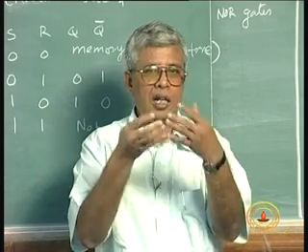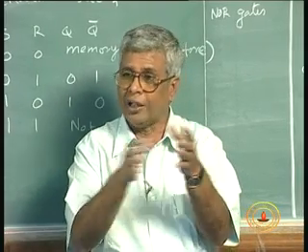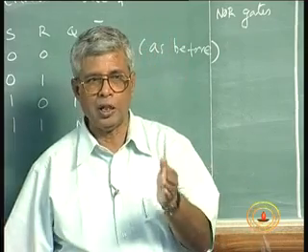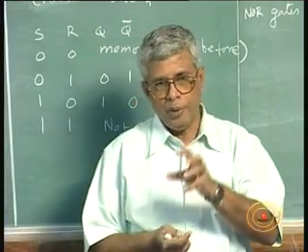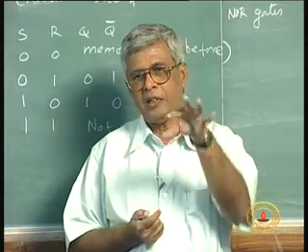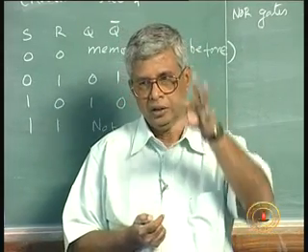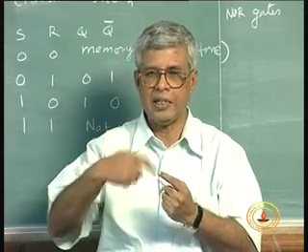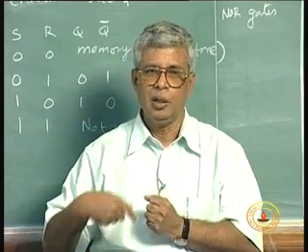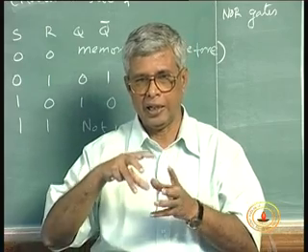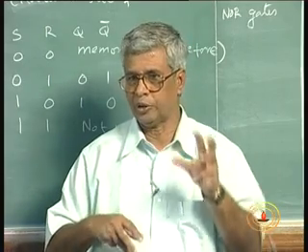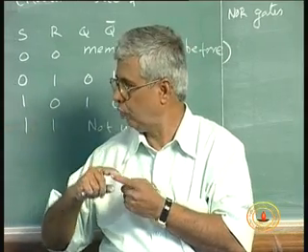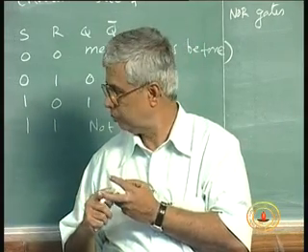So, our combinational logic theory, whatever we had seen, is not useless, it is required. It is not as if combinational logic can be forgotten from today and sequential logic is what is needed. Combinational logic along with sequential logic make digital systems tick. Real systems will have both combinational and sequential. Sequential decides the sequence of operations. Combinational logic does the actual output requirement based on the inputs. So, both are required and the basis is done, but of course, we have a few glitches to sort out.